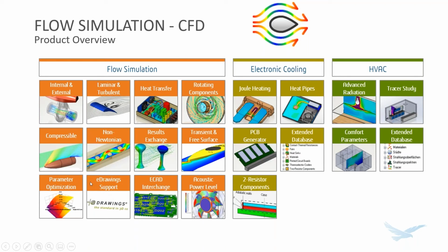Compressible and incompressible fluids, internal and external flow, combining CFD and FEA results, even free surface, all that stuff is available to you there. But it's also got some additional modules that you can add into it depending on what you need to achieve in the software. So if you're in the electronics industry, designing enclosures of things of that nature, maybe you've got PCB models that you want to incorporate, Electronics Cooling is able to gain better insight, use more flexible material types than you can with just the sort of standard package. So think about some of that if you're looking at industry-specific applications.